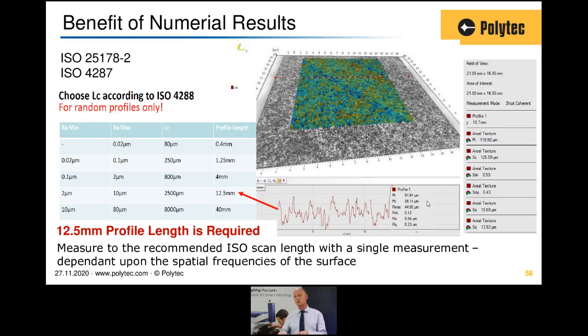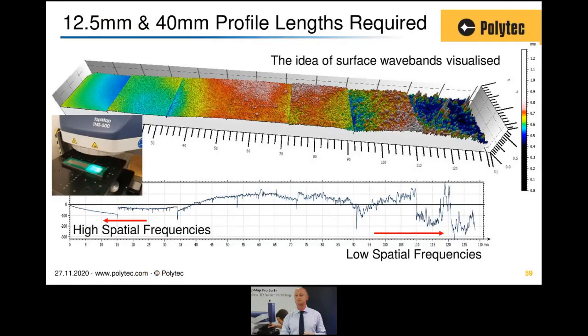So within one single measurement, the macroscope can measure a large area, and you can see I've trimmed this data set to represent 12.5mm, and that's one measurement in one go. A microscope type system would have to do a lot of stitching. So the time saving for the macroscope, if you have good representative data, could be good enough for acting as a roughness indicator for these very complex surfaces.